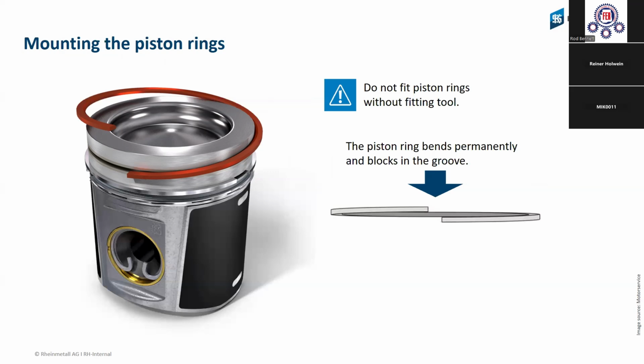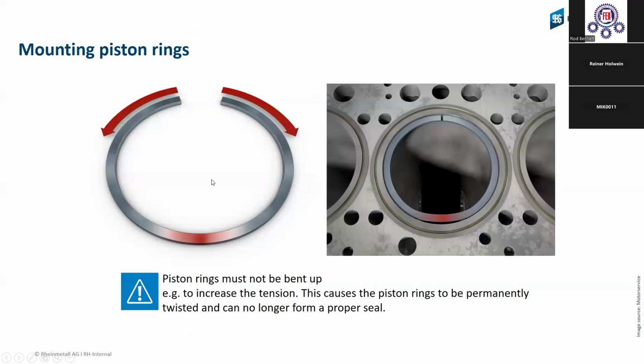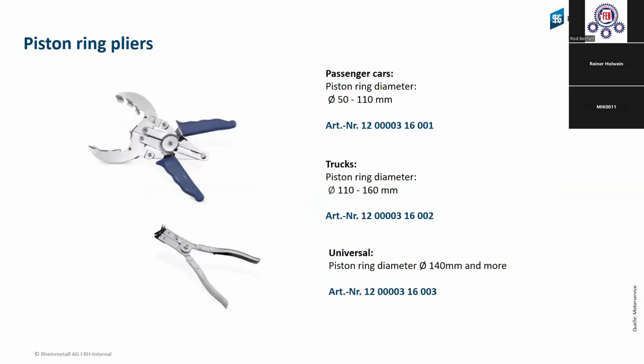The biggest problem, which you see on the next slide, is when we over-tension the ring. When we take the ring too much, when we take it inside the piston, then, as you see in the picture itself, it will not be sealed. It will not be sealed maybe after 50,000 kilometers, and not sealed at 100,000 kilometers. It will start from the first second with oil consumption, and everybody thinks, oh, I have oil consumption. And maybe the right tools were not used to assemble the piston rings.